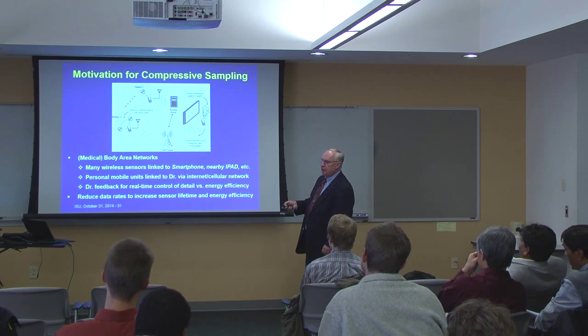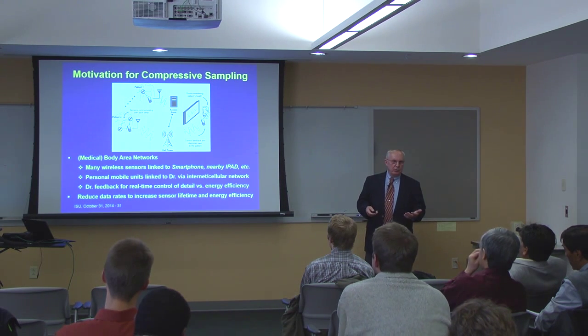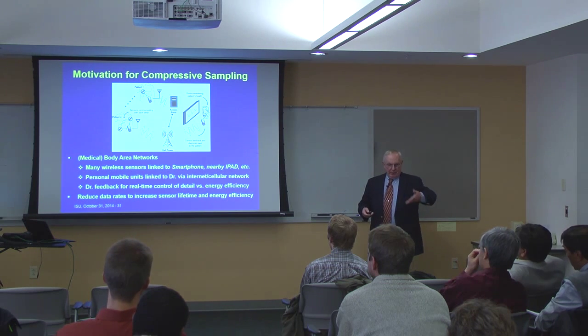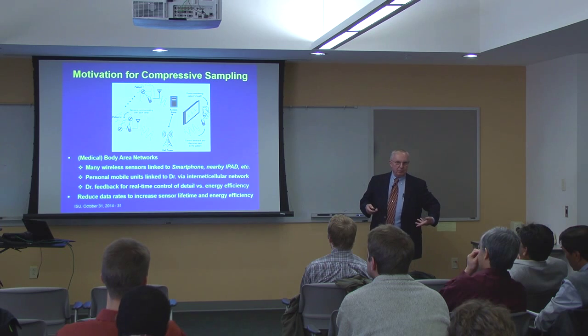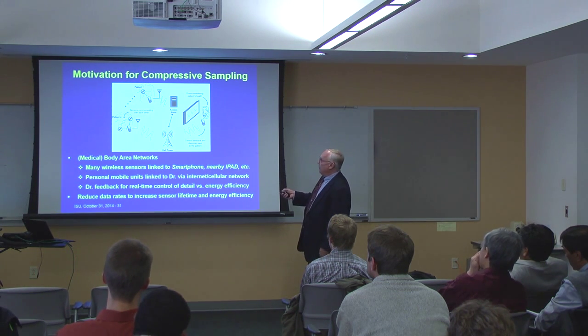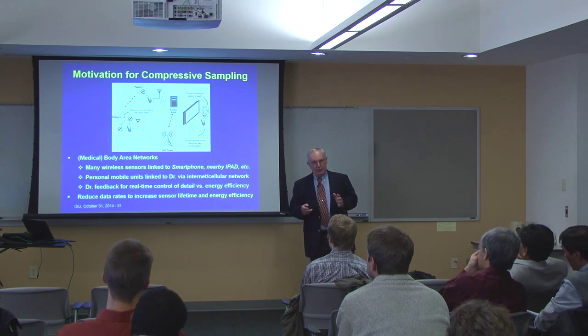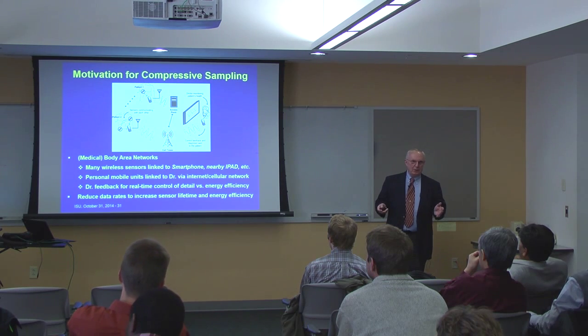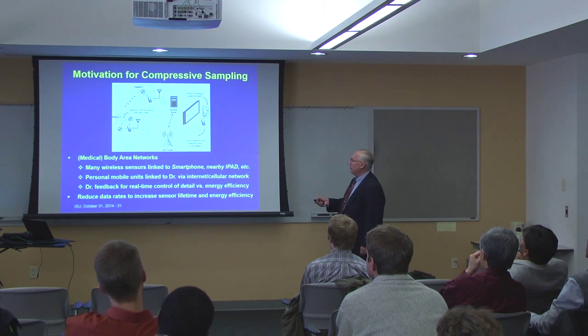Now, if you look at this system, like an RF system, what consumes most of the power is the so-called power amplifier. Even for this thing, it's called a power amplifier because it's sending an RF signal a couple feet to your cell phone. So if you can do anything to reduce the amount of time that the power amplifier is on, listen more than you talk, you'll save energy.